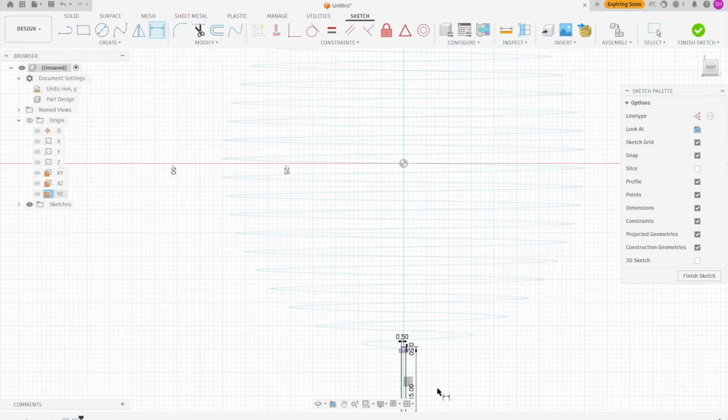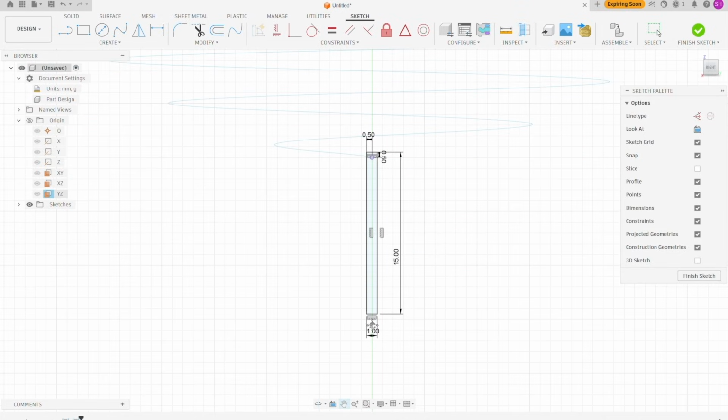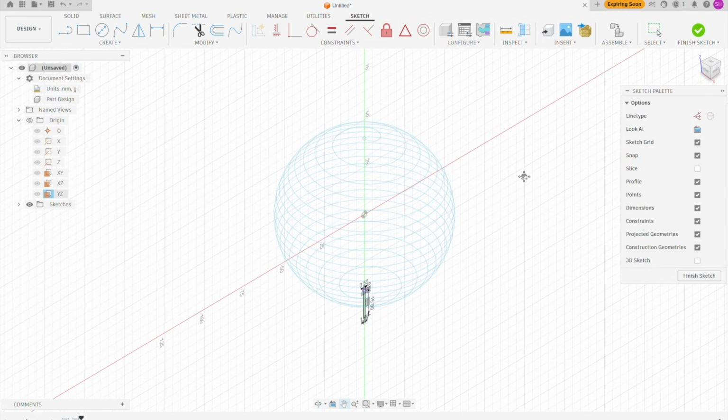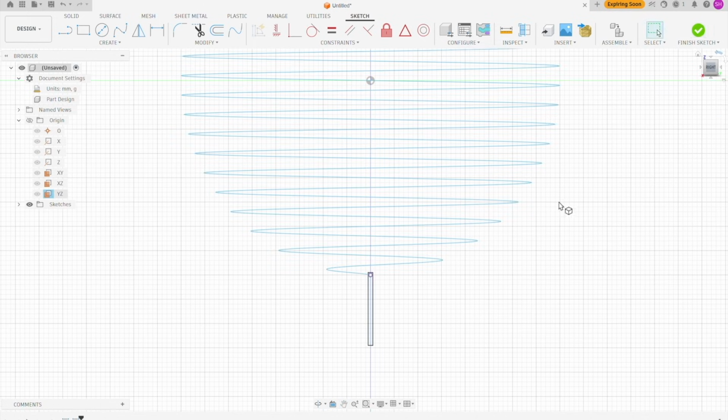So when you see black, I can use pen here. When you see the outline turning black, it means that the rectangle is fully defined. Another tip is to use this home button, which gives us an overview of 3D. So I can just finish my sketch here.